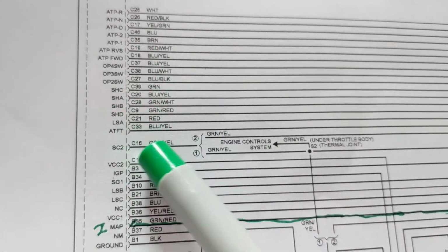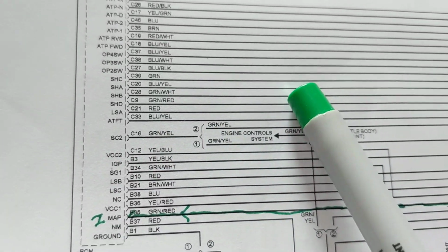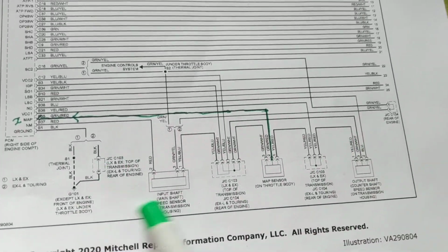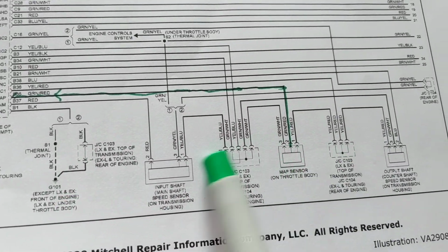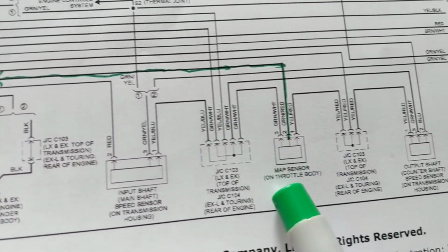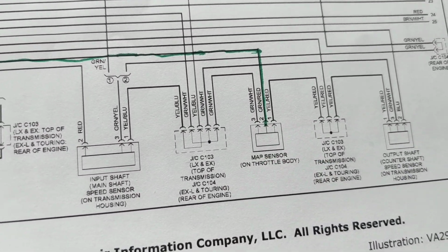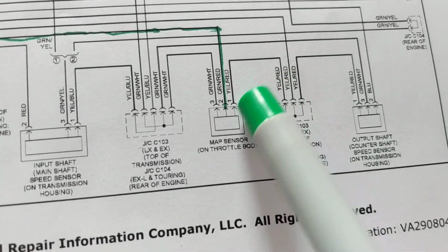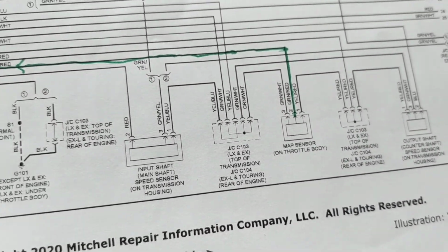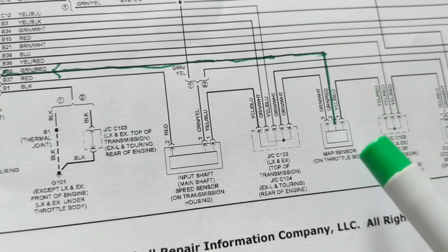Anyway, now let's look at the other ones. Like I said, look at all these abbreviations. We don't know what they mean. They go to other lines. We won't be concerned with that. We'll be concerned with whatever is visible on the page: any sensors or component symbols, whatever is here, that's what we're dealing with. So the famous MAP sensor over here. We know one of the lines has to be a signal line back to the computer, because it's giving information to the computer.